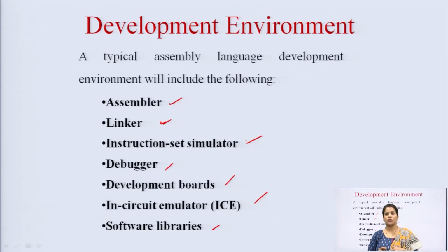So, according to the processor that we are using, this simulator software will simulate all the instructions, debug them, and judge the nature of the instructions related to that particular processor. So, this is the work of the instruction set simulator.